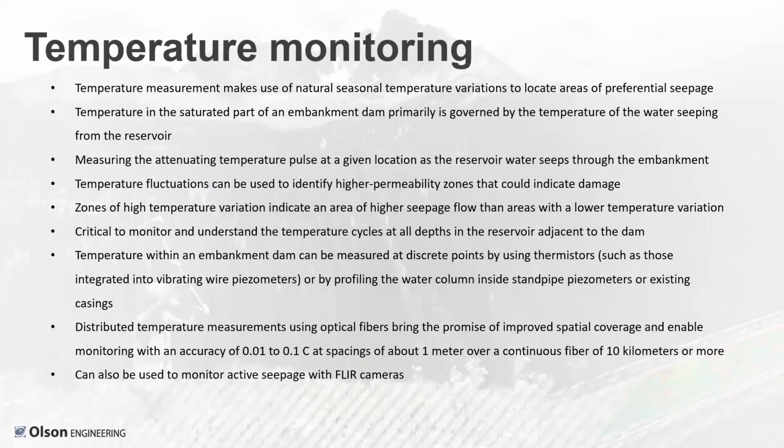All right, temperature monitoring is a method that's also pretty powerful for looking for issues on earthen embankment dams. We're looking at the difference between the bulk temperature of the dam structure itself versus the variation in temperature that could be caused by seepage coming through the dam.